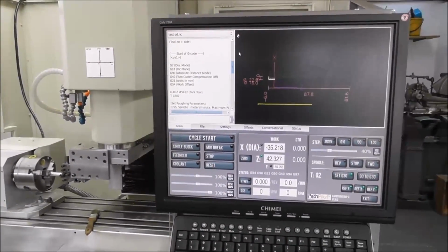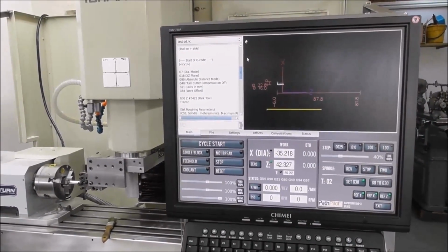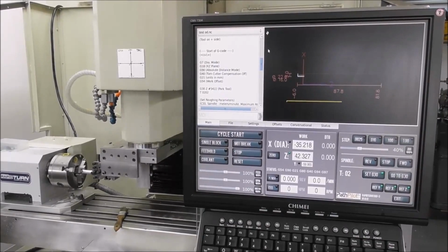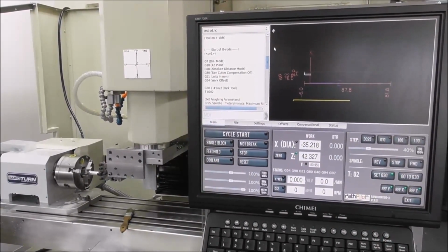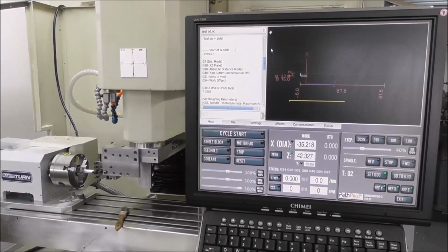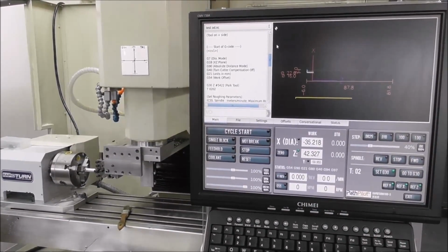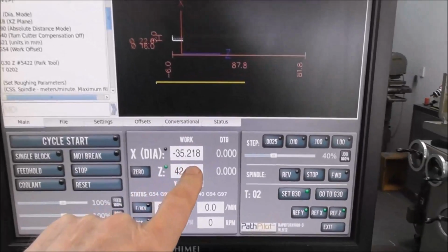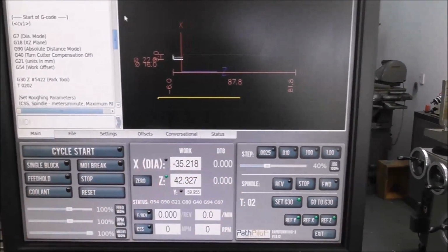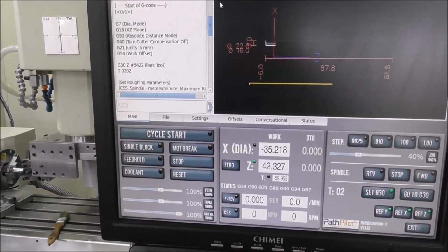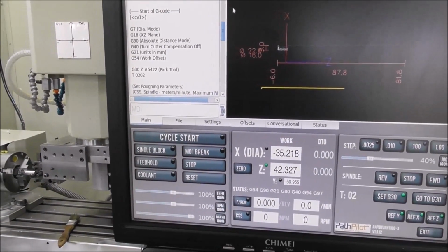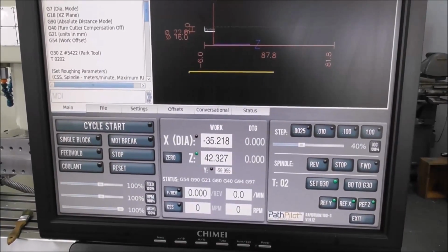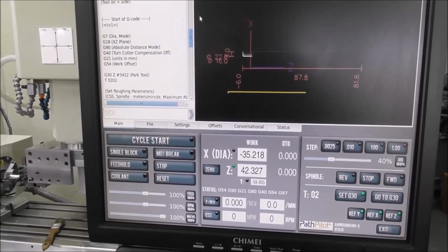Okay, so just reiterating one of those points. So you come in the morning, your machine's been switched off overnight, it's a lot colder, you reference it, open up your file, run your first part and measure it, and all of the dimensions have shifted slightly because of the temperature difference. You want to make an adjustment to fix them all. You don't want to have to individually reset all of the tools. Well, then you would go to, for example, your master tool 1, if you're using that system, and change the DRO here by that small amount. And what that will do is shift all of the offsets by that small amount. And let's say it's 2 thou different. You would change your DRO or shift the work in the direction you want to go, and re-zero the DRO, which is probably safer. It's less likely to get your plus and minus mixed up. And then all the different offsets will shift.